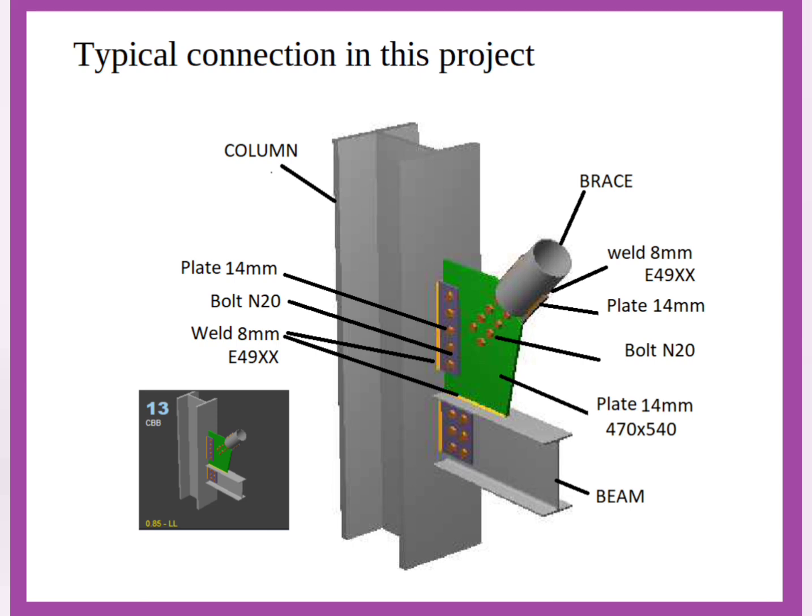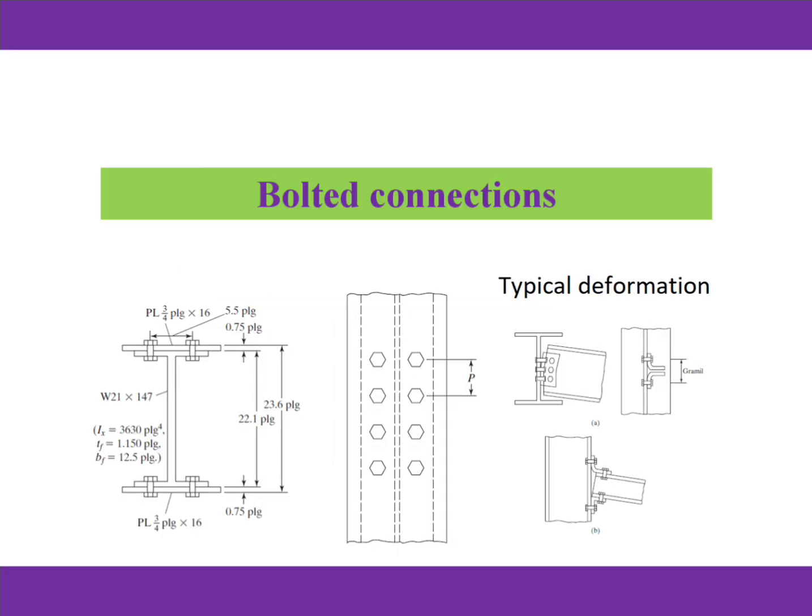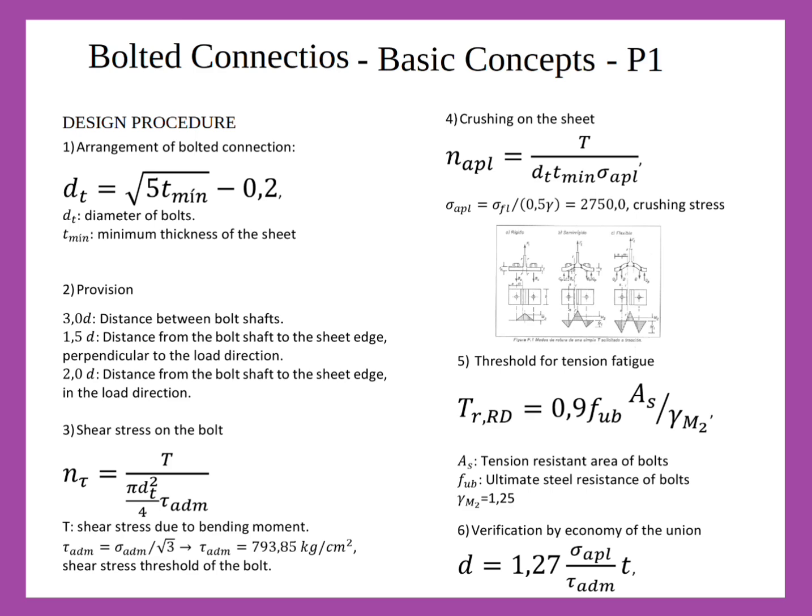So let's get started. The main function of a connection is to hold the parts of the structure together, supporting both their own weight and the load exerted upon the structure by external loads. A defective connection can also cause total collapse. However, they can also be designed for other purposes, such as dissipating energy. In order to properly design connections, the minimum load and the strength requirements must be consistent with the standard for connections. Wind, seismic, operating and gravity loads must be considered in the analysis.